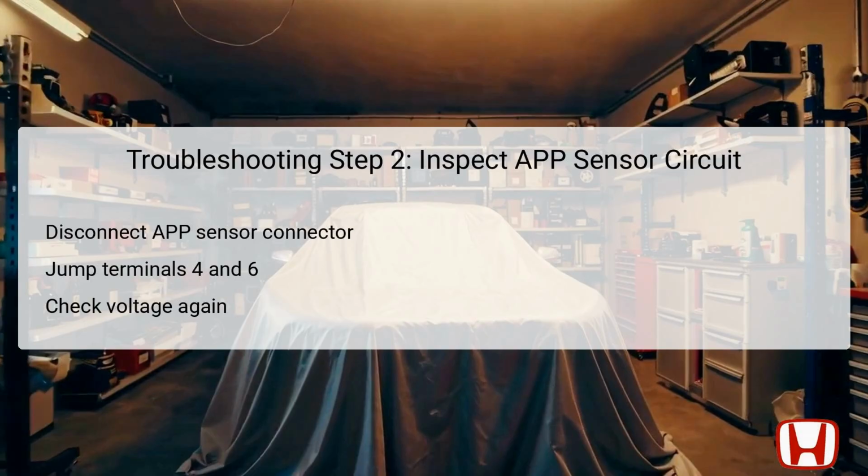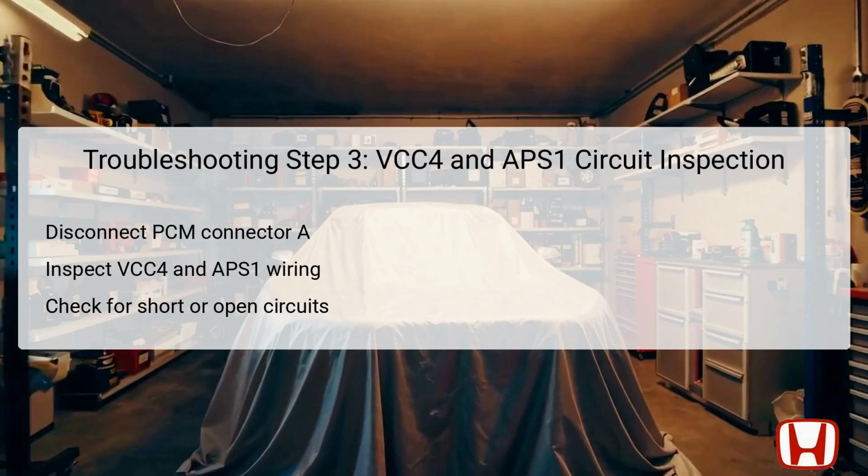If the voltage now exceeds 0.2 volts, the issue is likely localized to the APP sensor itself and its connection to the PCM. The third step involves inspecting the circuits related to the APP sensor, particularly the VCC4 and APS1 wires that connect to the powertrain control module, PCM. First, ensure that the APP sensor 6P connector and PCM connector A are both disconnected. By checking these connections, you can eliminate any potential faults stemming from loose or corroded contacts.